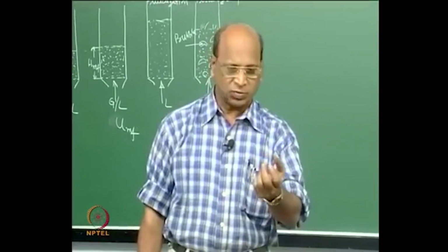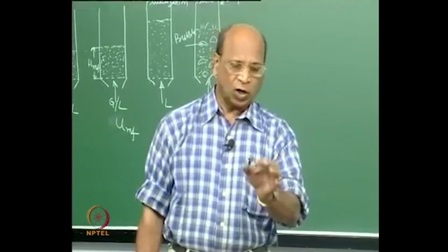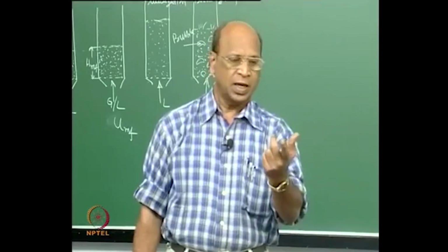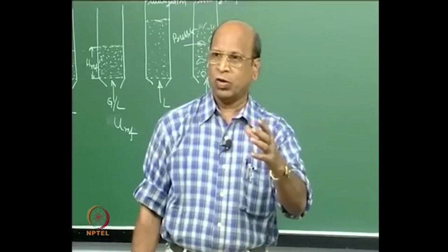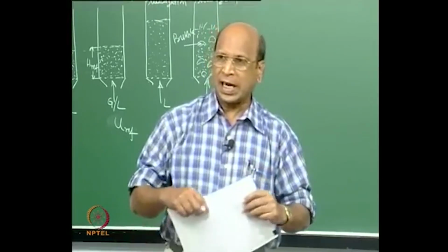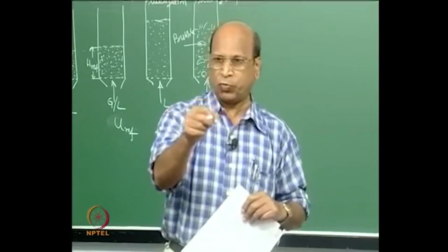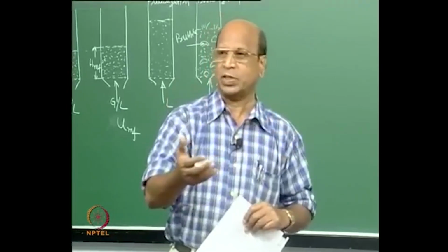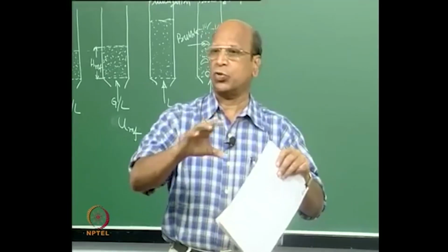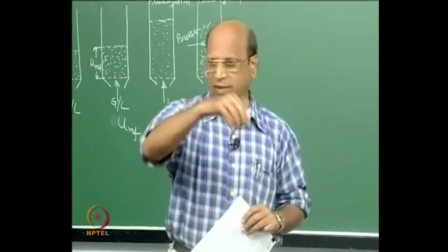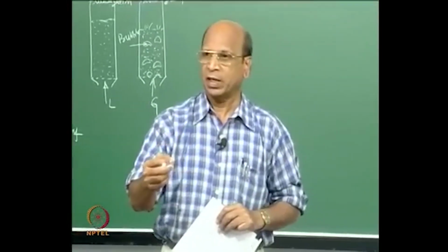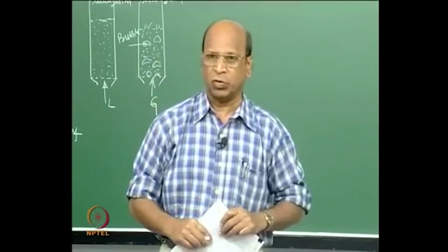Why a fluidized bed is very good there is that you can have small particles, number one. In a packed bed you cannot have that kind of particles, and number two, surface area is more. So the rate of leaching will be very high, and on the other hand every particle will be uniformly fluidized, particularly when you have a liquid system. Then on the whole each and every particle is uniformly leached out. Like that there are many examples which we can give.